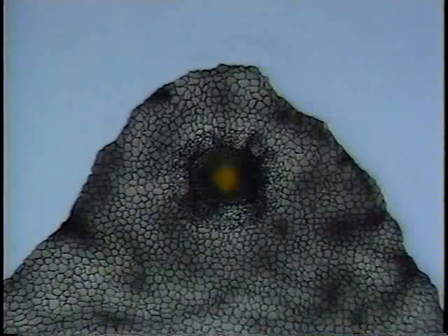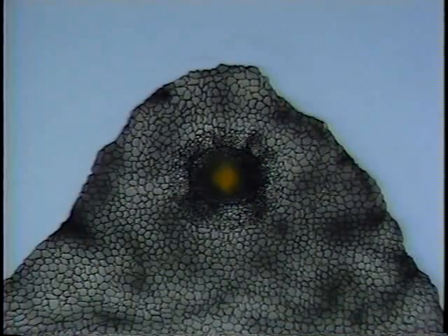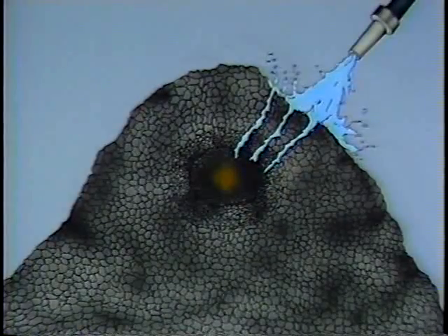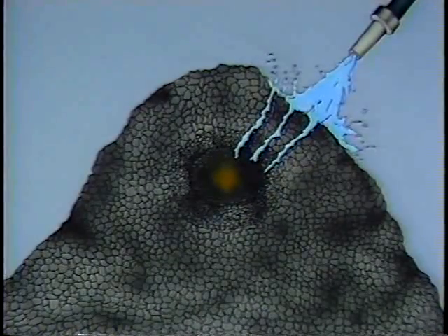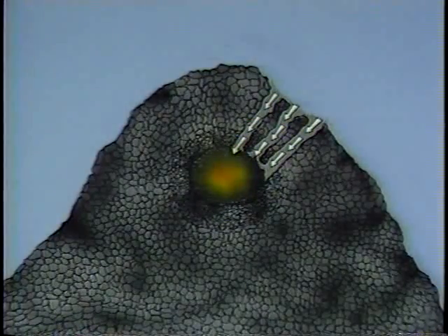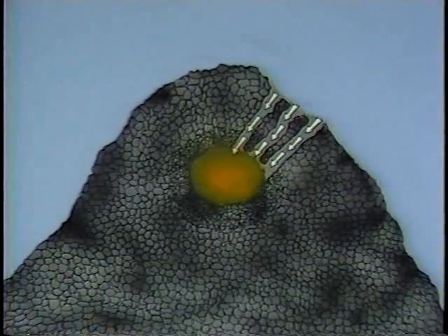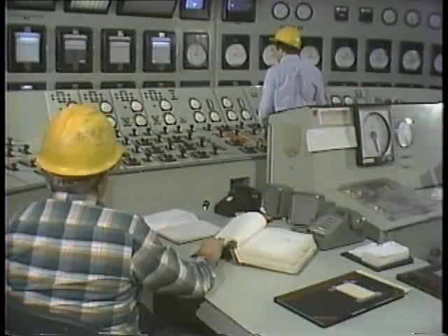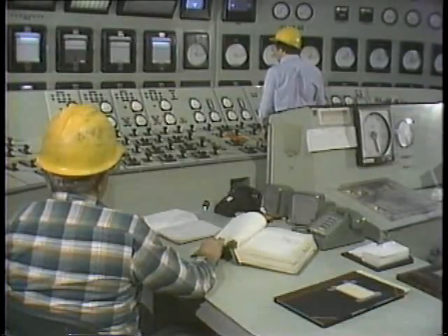Fires in bunkers and coal piles generally occur deep down in the coal. Water has to filter through the chunks of coal to get to the fire. In doing so, the water can cut passageways for air that can actually feed the fire and increase combustion. In all cases, your plant will have specific procedures that you should follow when dealing with equipment fires.